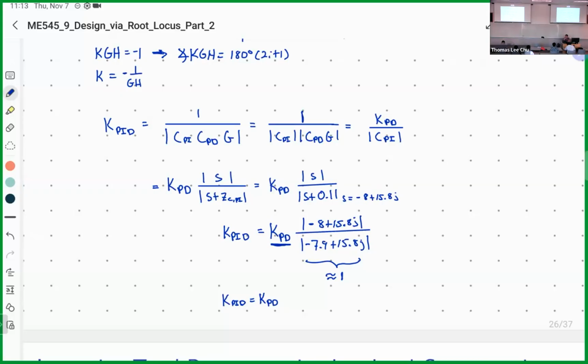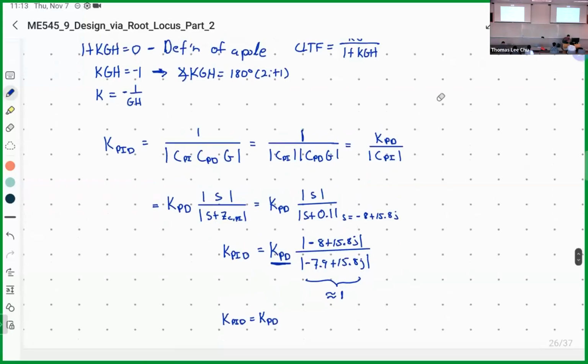How do we increase the accuracy? If you want the root locus to not change that much, put the zero really close to the origin. So instead of having it at 0.1, you could have it at 0.05. Then the root locus will change even less. But then the issue you deal with is really long convergence. You'll probably see this versus 0.1, which is probably going to be like this. Well, that wasn't a very good example, but kind of like that.